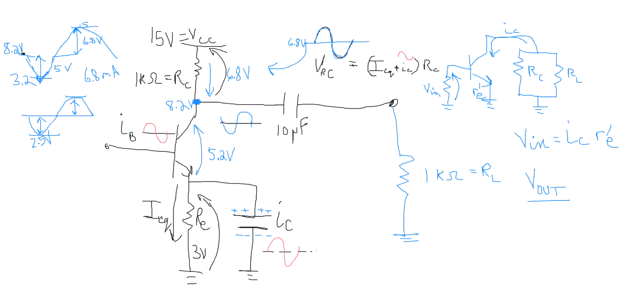Okay, first we're going to write just a simple Ohm's law. Remember, V out is the collector to emitter voltage. It's that voltage there. And according to Ohm's law, V out over the parallel combination of RC and RL is going to be equivalent to IC.